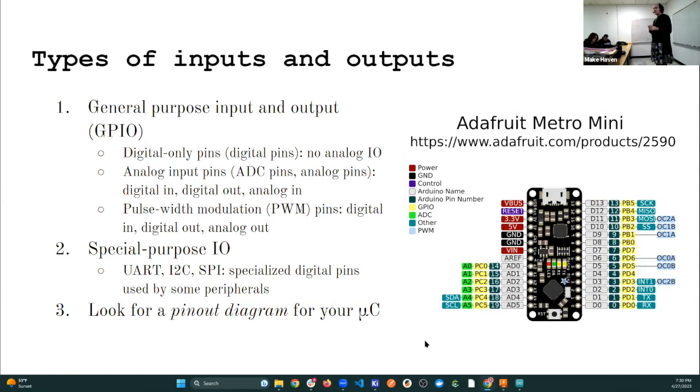What's up? So I see 14 pins on each side of the microcontroller, yet I see what looks like 40 pins in that key, the color. How does that happen? What's happening here is that, first of all, some pins are multi-purpose, and second, some pins have multiple names. So this pin down here, which is called pin 19, is also called A5.